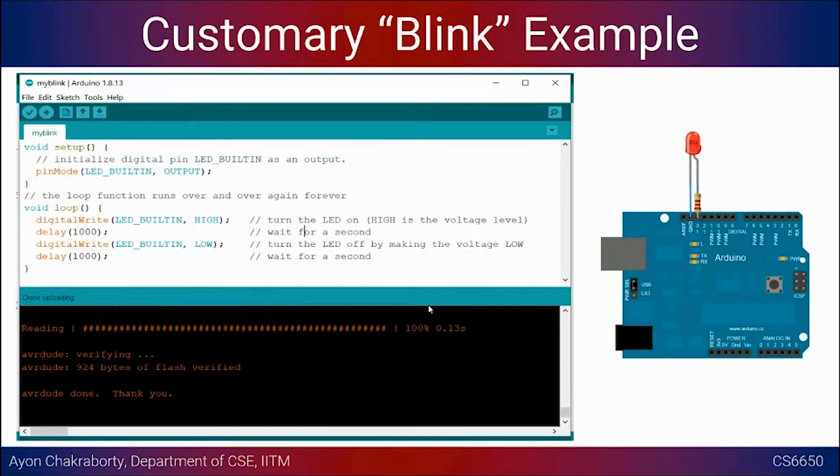Okay, so this is the actual program, and as I told you, if you have an Arduino at your disposal, you can simply run this program and see what is going on. And LED_BUILTIN is nothing but a macro. It just says that it is going to turn on the LED that is built in on the device itself, which is connected to pin number 13. So I would request all of you to at least try out this program and see that all your configuration and settings are correct and you are able to run that without any errors, right?